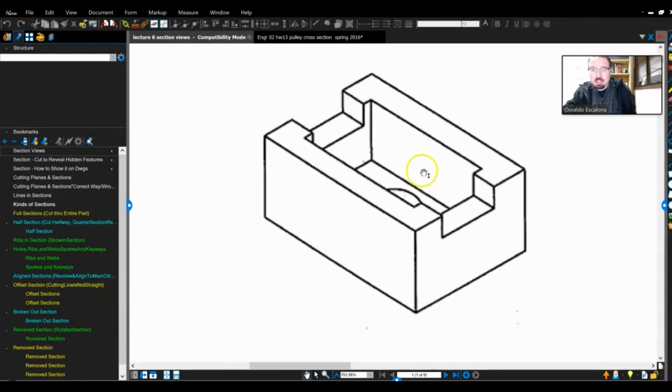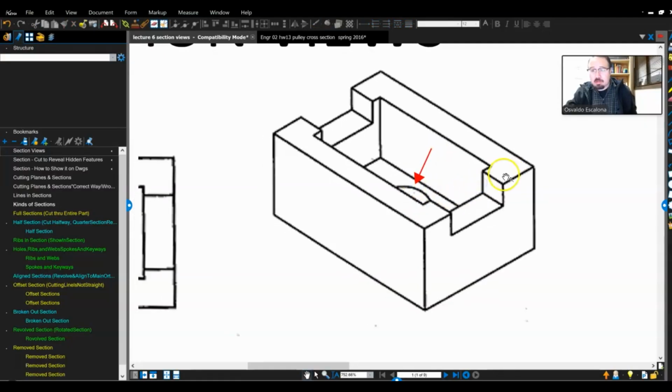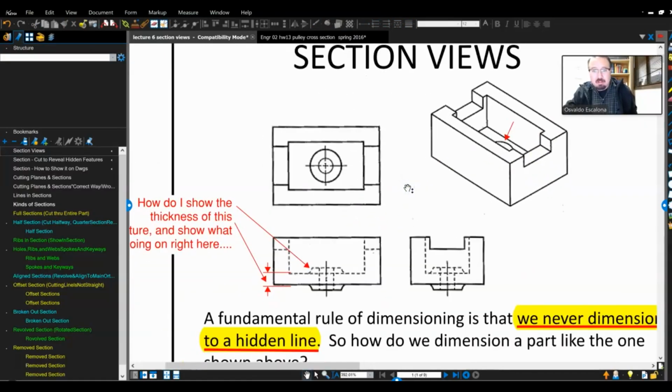So, for example, in this example, it's kind of like a box, and it has one slot on both of the sides, and it has a certain thickness and something's inside of it, right? I don't know what's inside of it. Let's start looking at the views. Based on the views that I have seen, it seems that it has a cylindrical protrusion, top and bottom, and it seems that it has a hole that goes all the way through, right?